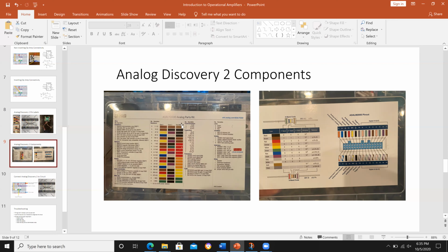But what you are going to need is resistors. So here's all the resistors that they provide you. And they tell you the quantity, the value, at least the nominal value. Remember, there's going to be some variation. Then they tell you these 3 bands, right? You're like, oh, what are these 3 bands? What do they represent? On the inside of this lid, you get this nice little chart here. And what the bands tell you is you actually have 4 bands. They just disregard the 4th one, which is the tolerance.